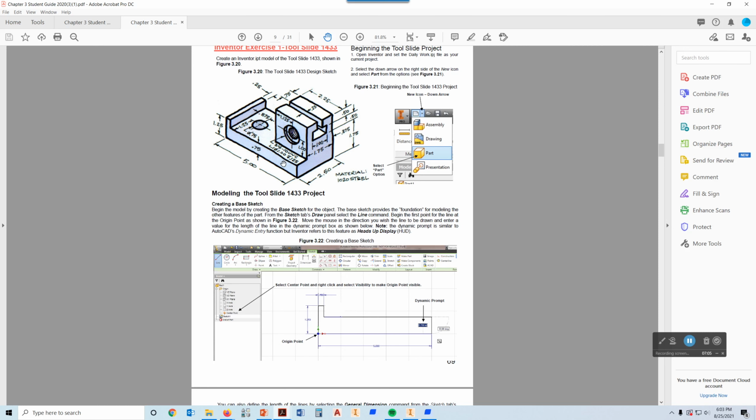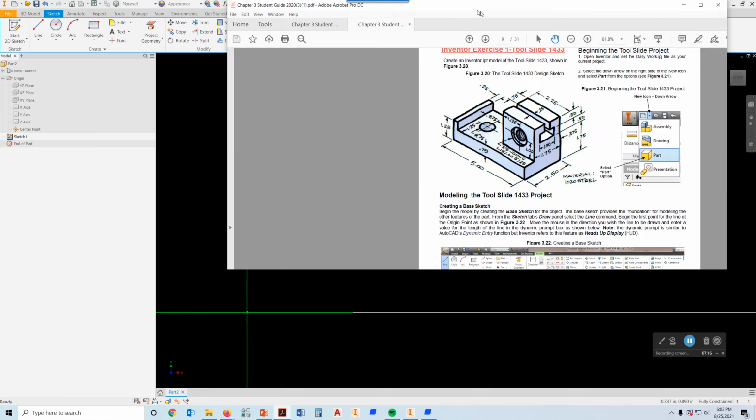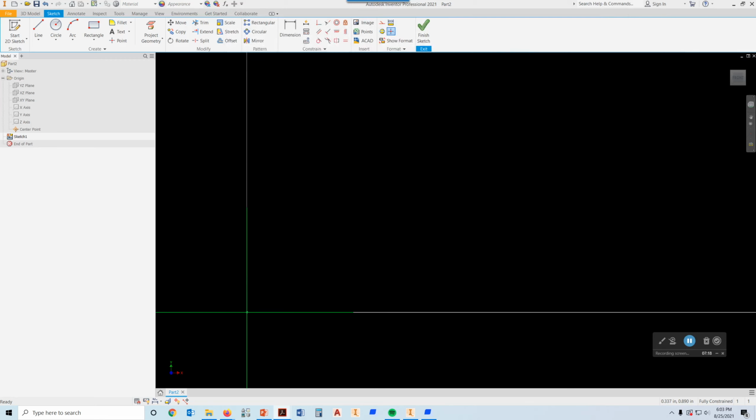And then I would extrude that 2.5 inches deep, because that's how deep this is. Then I would add this other stuff to my base model, okay? So that's what we're going to do. We're going to start by drawing that profile right there. So here's how we can start. We can start by picking on our rectangle command. Pick on rectangle, and it wants to know, well, where's the lower left corner, for example. So I'm just going to snap right there onto my origin point and come off of that.